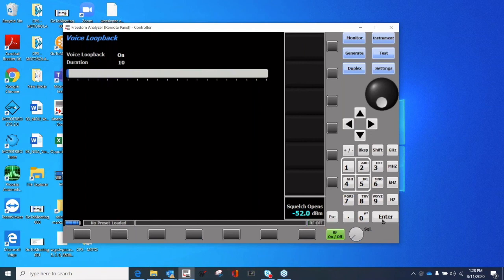You check the whole path through the analog modulation, where your voice passes through the vocoder, is transmitted to my R8100, recorded, and sent back as a package to the radio, which demodulates it into analog voice, and then you can hear what the modulation sounds like. So this is a good test and a very quick point.